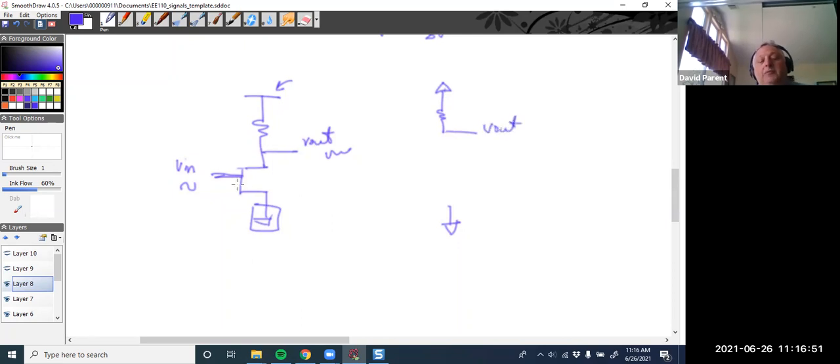Now, what do we do with this transistor, right? And there's all these nonlinear equations, but now we're at one point and we're taking the derivative of it, right? And so remember I said, if I change this, I'm changing the current, right? So it's a voltage controlled current source.